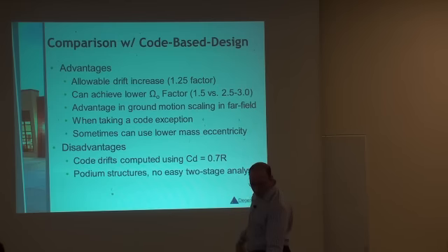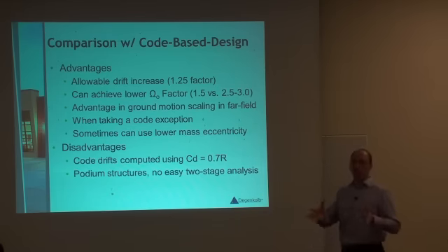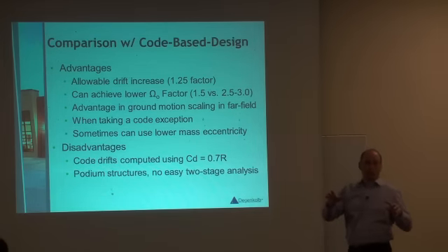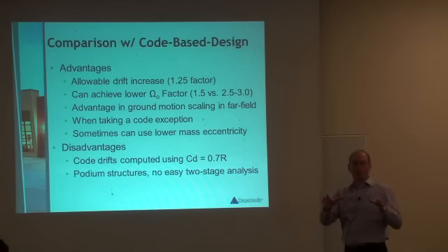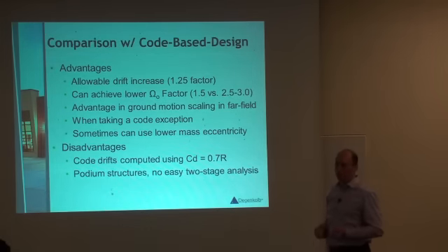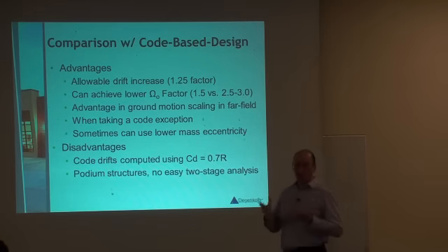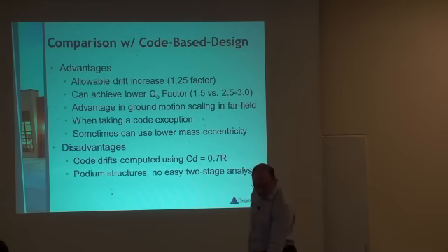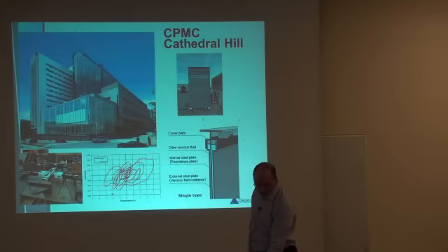For podium structures, it's still a problem to use because very often it's very difficult to model the full building. This is when, say, a steel building is sitting on a large parking structure or podium structure that's usually made of reinforced concrete walls. To model the full thing inelastically is still very expensive in many cases, but there's no easy way to really do a two-stage analysis. We've tried that, but it's very problematic.